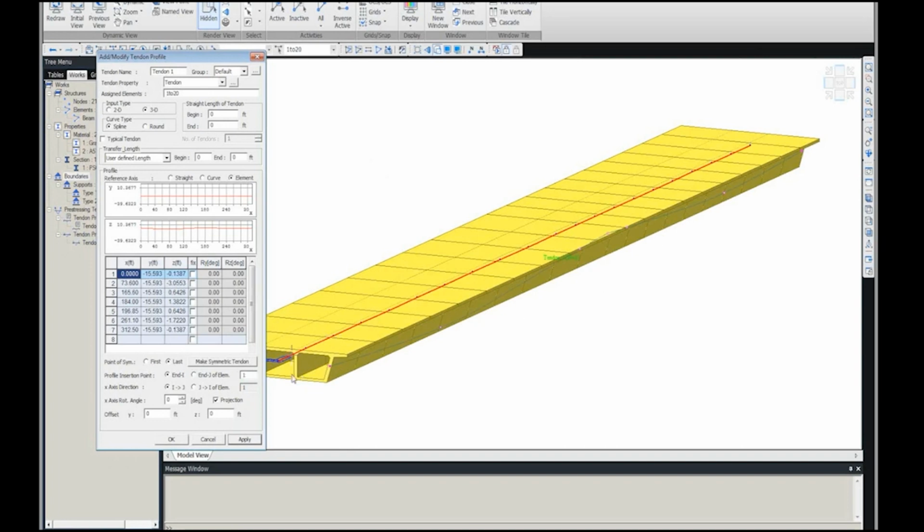And there is just one thing. I'm going to fix it later. But let me enter the rest of the tendons. I call it tendon 2, bringing in the coordinates. Delete and bring it here. You apply it on the same elements and apply. Okay, tendon 3 will be the same thing, only the Y will be positive.